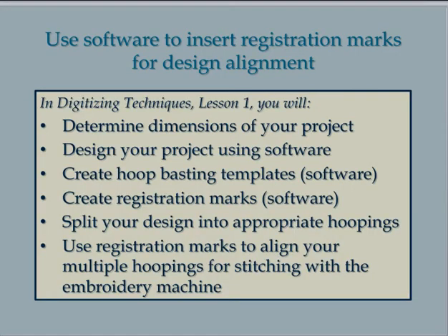This lesson will step you through the process of splitting an oversized design using generic digitizing software techniques. The process begins with establishing the measurements of your completed project. Then you digitize the design using software tools to split the design and create alignment guidelines. Finally, stitch the design with the aid of the alignment guidelines.